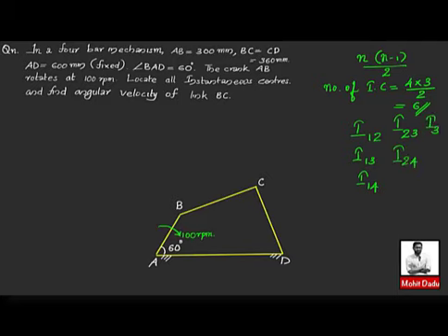Similarly, I31 will not be there, already we have I13, I32, already we have I23, I33 will not be there, and then you have I34. And next I41, already we are having I14, I42, I24 is there, I43, I34 is there, and there is no I44. So the 6 instantaneous centers are there, and we have named all of them here: I12, I13, I14, I23, I24, I34. And you have to mark or locate all these instantaneous centers on this 4-bar mechanism. That is one part of the question.